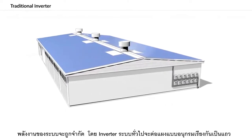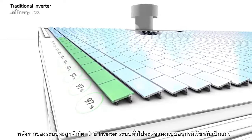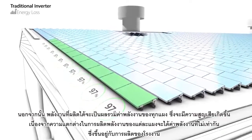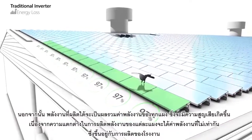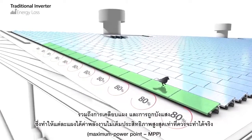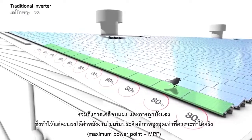Although traditional topology using string inverters is still used in the majority of large-scale installations, it suffers from a number of significant drawbacks. First, the system power output is limited. In traditional systems, panels are wired in a series as a string. Each panel has its own power production profile. This is a function of its manufacturing variables, installation parameters, and shading patterns. This means that panels don't usually work at their maximum power point.